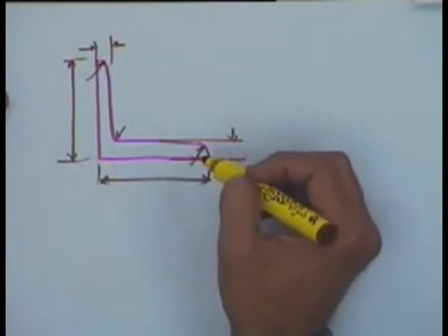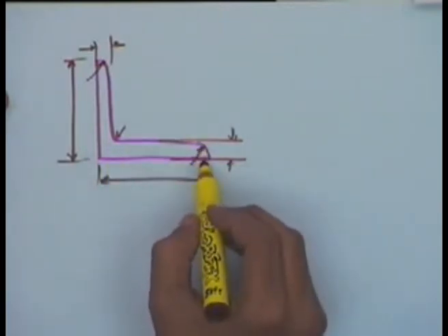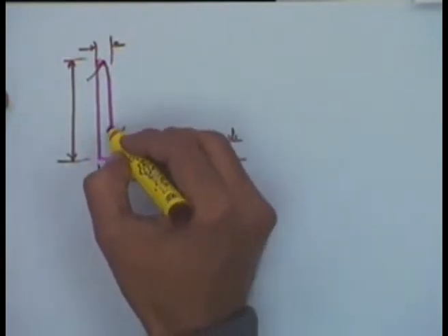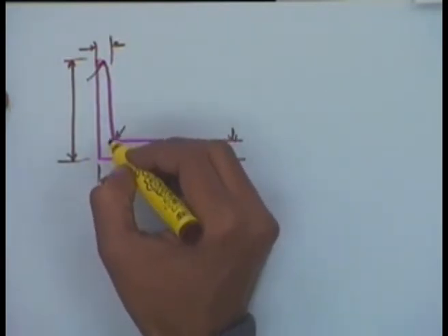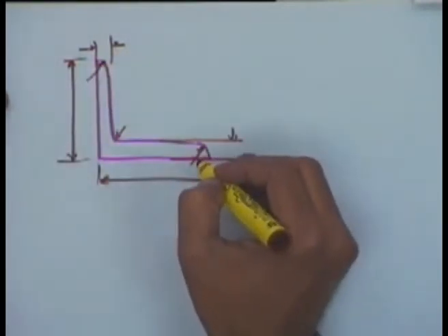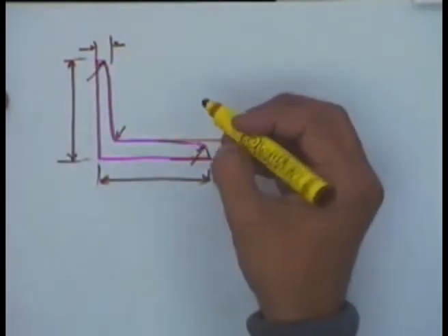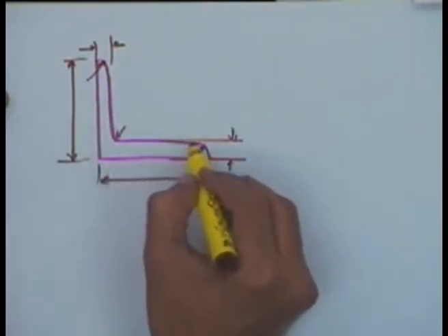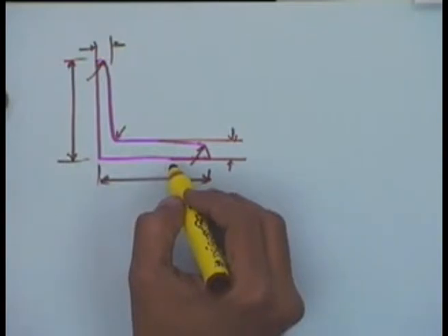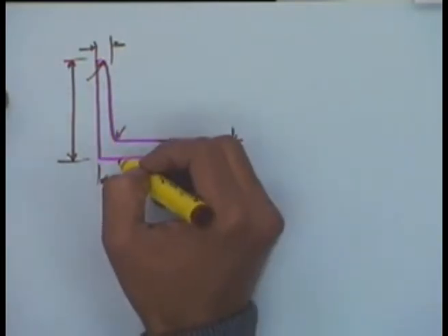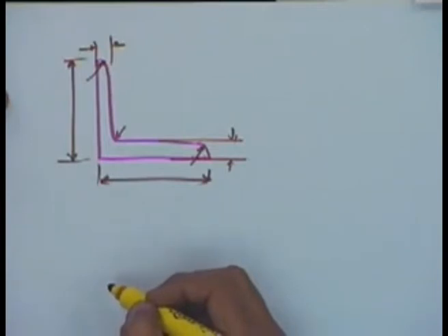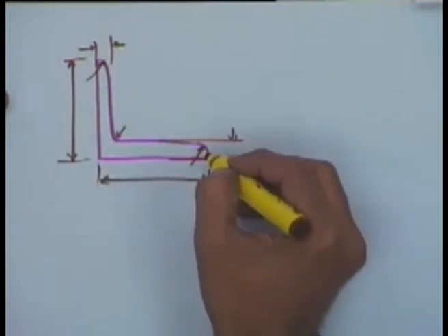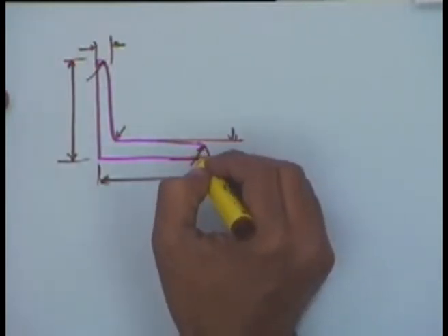Making an angle like this would mean that I'll first take a plate, horizontal or vertical plate. I'll take the union, then I'll take a fillet over here. Then maybe I'll take another fillet here, and so on. Plus this angle can also have a draft over here. That will complicate matters even further. Every time I have to make an angle, one would normally not like to go through a sequence of steps like that. So what is often done is we make primitives which are complex objects like this.